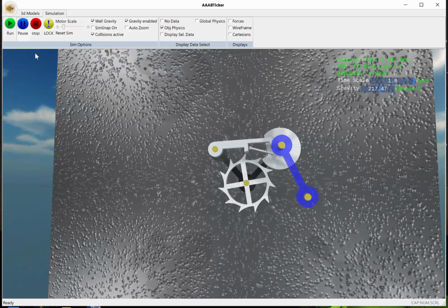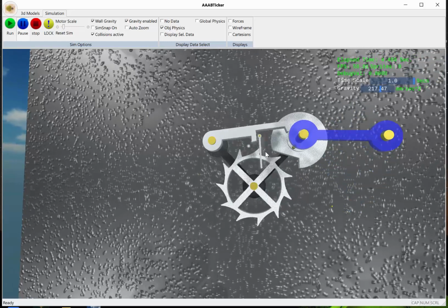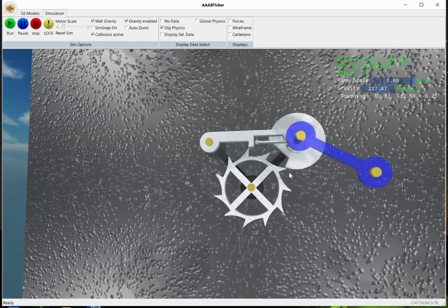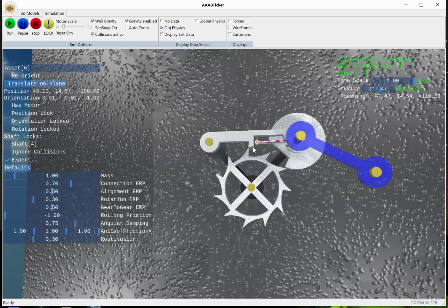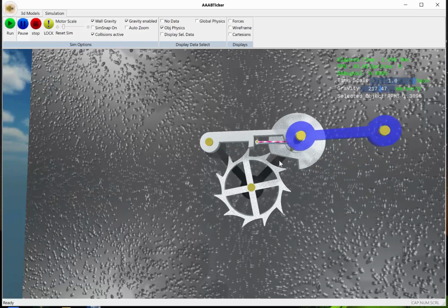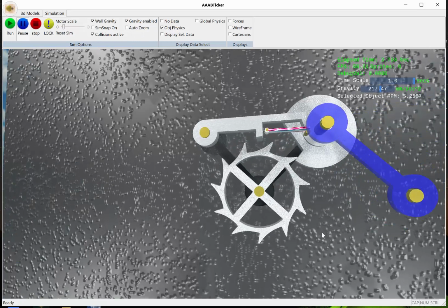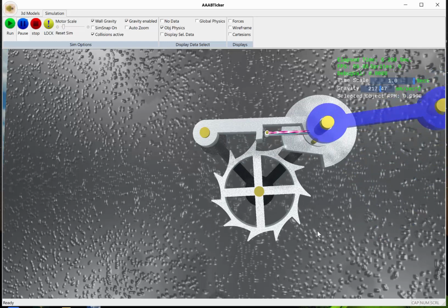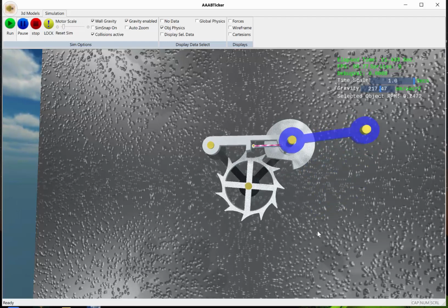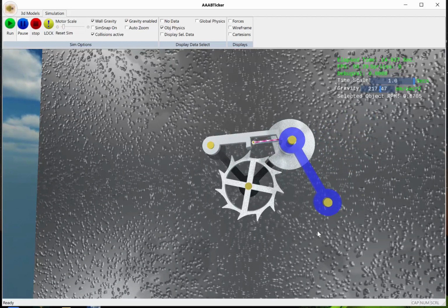I don't know if anybody can guess what's going on here, but if you look at this fluttering valve, it's not properly sticking up, nor is this pulling down. If I, however, select the pin and tell it that it is locked to its shaft, but on a spring, I can give it a grounded spring, give it some strength, turn the spring position there, and now when we run, you can see that the spring goes back up on its own, and it begins to tick, as you would expect. So with proper masses and proper accoutrements to it, we just built an escapement.